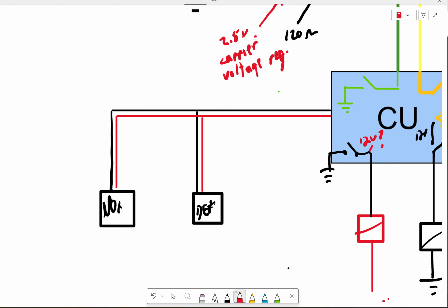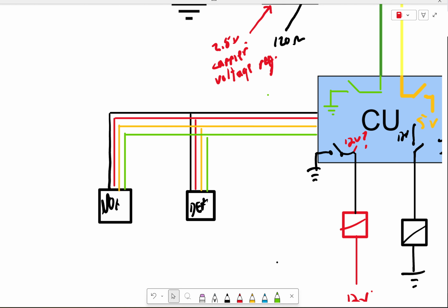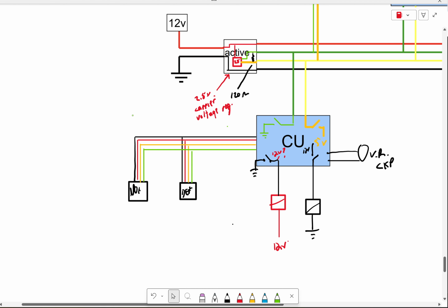There we go. Now, what we don't do is send individual commands to these modules. We just connect them via another CAN bus network. This CAN bus network is specific to these modules. So yes, it is a CAN, but no, it's not part of the main CAN bus system for this machine. So you have what could be called the vehicle CAN, and then over here we have this secondary engine CAN, okay? So this right here would be a secondary CAN bus.